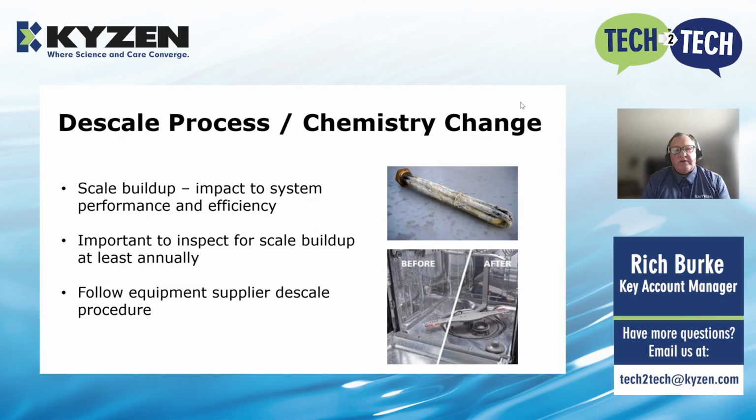If you're interested in learning the details behind a descaling process, please reach out to us. We can share that with you. But from a basic standpoint, what one would do is first drain the wash tank, do a mechanical clean out of that wash tank, fill it with water, fill it with the descaling solution, and run the descaling solution at the targeted concentration and temperature for the amount of time recommended by the supplier of that descaling solution.